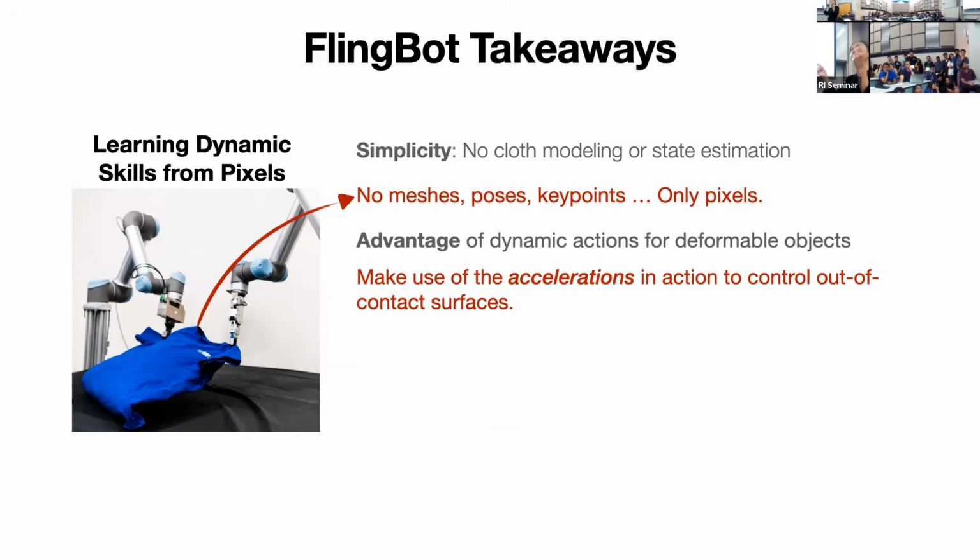And then one way to think about it is that you kind of front load the complexity in the grasping stage. And then the actual fling action is pretty open loop. If you think about how we actually do the fling action, we don't do a very detailed closed loop control for it. It's pretty much open loop. What we really need to plan is where is a good grasping location.